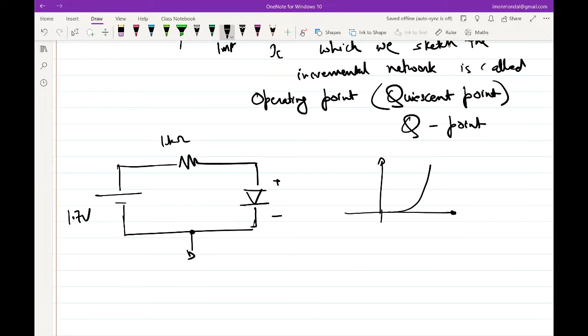currents, for a range of currents, we can approximate the diode with some fixed voltage. That's a numerical approximation, a numerical liberty that we take, but with the understanding that it's not entirely accurate. So let's say you have done this using numerical calculations, or put it in a simulator, and you found that if you hook up a diode like this, you end up with 0.7 volt across the diode. This is numerically gotten. Nothing fancy about this.